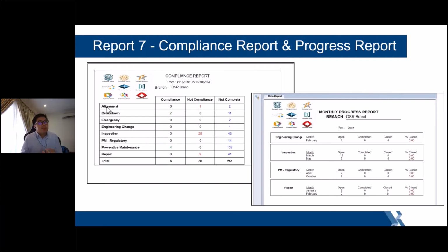So if you are tracking maintenance via our CMMS system, you know that for each maintenance task, if you need to complete it in 24 hours, the high priority job, then the technician will need to complete it within that 24 hours, right? If the technician completes it 2 or 3 days after, then the maintenance task will be non-compliant. So you're able to track your compliance of all your maintenance tasks in your plant. So I think this is quite important, because without this type of tracking system, you will not know, right, if the high priority jobs are completed in time or not. Okay.